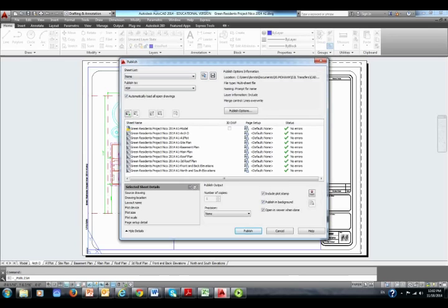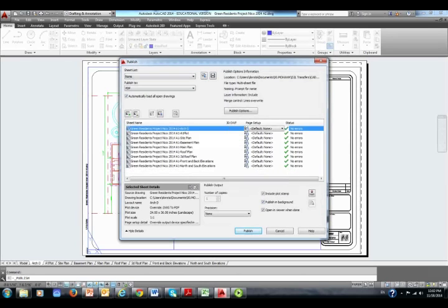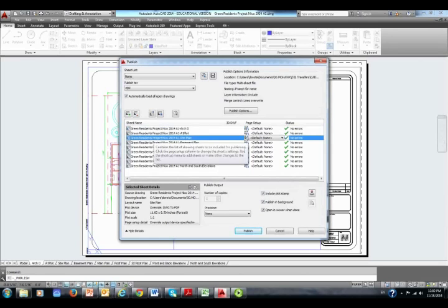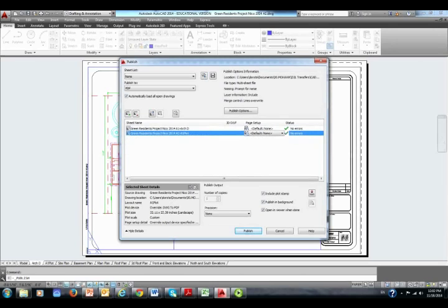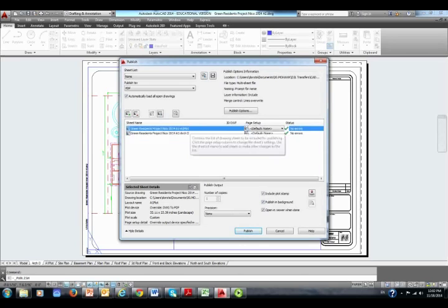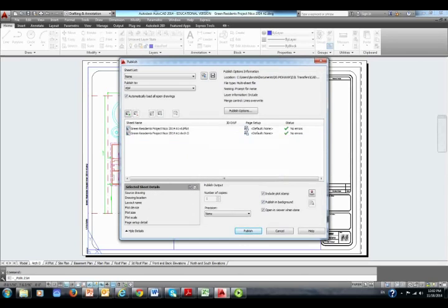And the most important thing here is picking out what you want, what you don't want. I don't want your drawing. I want ArchD and nothing else. So I'm going to delete all of the other plans, and I'm going to go in order ArchD or A1 plot, or you can go the other way around. That's up to you. And we simply publish. Include plot. I have my standard stamp. Publish in the background. Open when it's done.